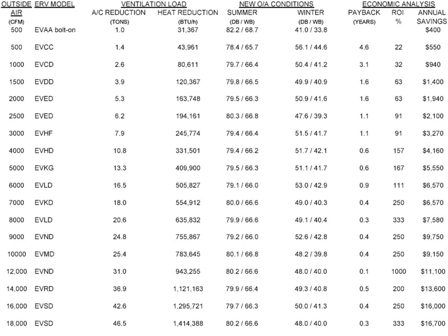This particular chart was based on 95-degree outside, minus 10 on the heating side, so it's pretty extreme days it was based on, but it kind of covers everything in our area if you do it that way. And it was based on someone upgrading their rooftop and buying a new, smaller rooftop with an ERV bolted to it or inside it or something like that.